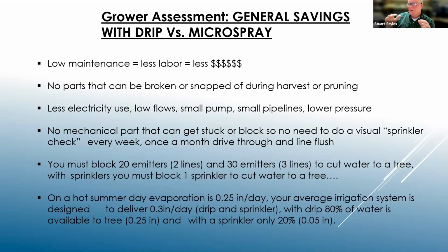Anytime he has all this equipment in the way, when they do tree trimming or the harvest operation, they've got to send a couple of guys and spend a couple of days touching up the irrigation system, putting the spaghetti lines back in, and he sees that as a definite advantage. It's just a matter of making sure that we can keep the lines in the right spot. The drip products require less pressure, so you can lower your pump pressure requirements, so you have less electrical requirements.